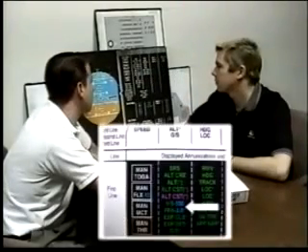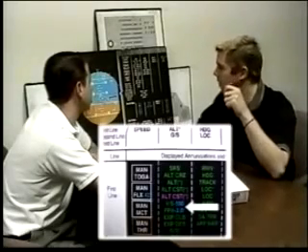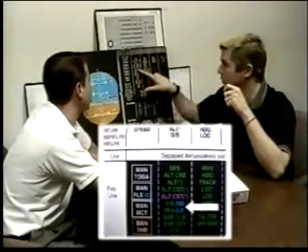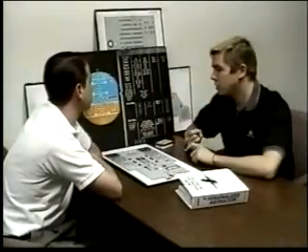Vertical speed and flight path angle. Well, they're maintaining some kind of flight path, either a variable type of vertical speed or some kind of flight path angle. To do that, we don't need just idle thrust. It may take idle thrust, but we don't know that we need it. And to descend, we definitely don't need climb thrust.